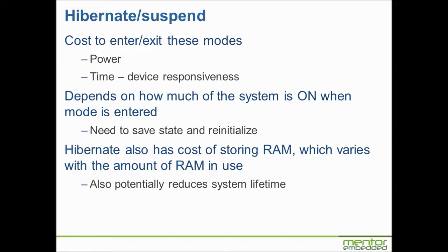That can be minimized by making your application as small as possible, so there's as little data to be saved as possible. You can even do clever things like, well, you only store the RAM data, not the RAM code, because obviously the code is not changed from last time. The code's fixed, but it may be loaded into RAM for execution purposes. So you only save the data, but when you restore the RAM, you have to restore the code and the data. So there is room for optimization there.